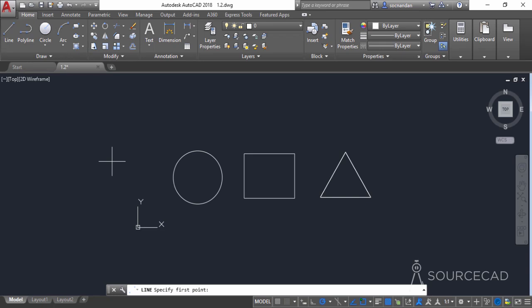Simply go to that command and left click, and the command will now be activated. Once the command is active, you'll notice that its name and also the instruction will be visible on the command line, and the cursor will change into this point selection cursor or into a pick box. In order to exit this, simply press the escape key. You can press escape multiple times if you want, and that will not make any change to the drawing.